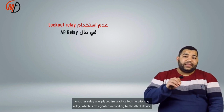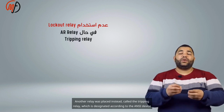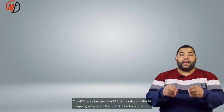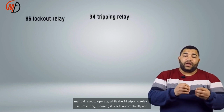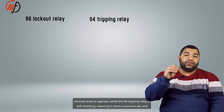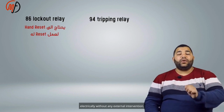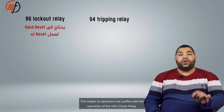Another relay was placed instead, called the tripping relay, which is designated according to the ANSI device code as 94. The difference between the 86 lockout relay and the 94 tripping relay is that the 86 lockout relay requires a manual reset to operate, while the 94 tripping relay is self-resetting, meaning it resets automatically and electrically without any external intervention. This makes its operation not conflict with the operation of the autocloser relay.